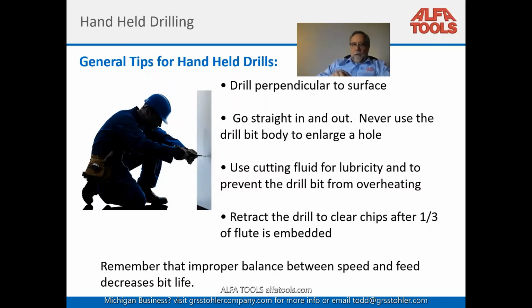Then if you're in there and you're drilling fairly deep, sometimes you have to retract the drill, clear the chips out of the flutes, and re-enter the drill into the hole. You can take it 1/3, you clear the hole altogether. This is kind of an operator thing, but you definitely have to balance the speed and feed for the drill to work properly. Let's see what else we have.